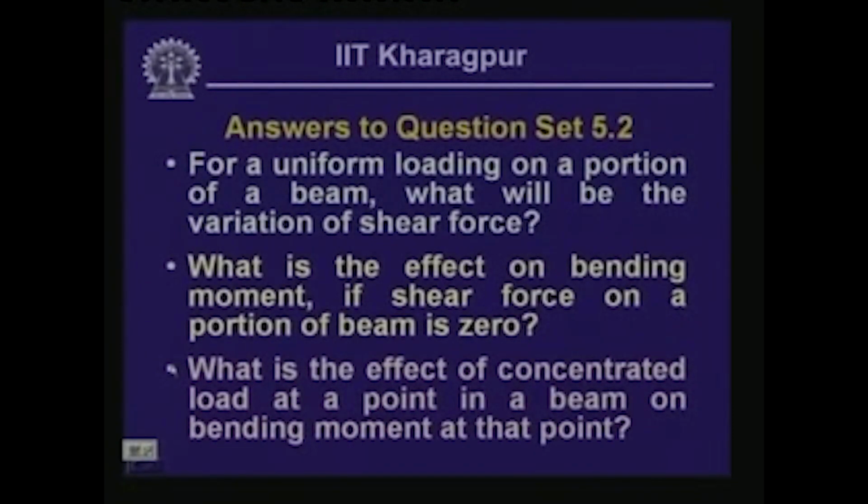Now, the last question was what is the effect of a concentrated load at a point in a beam on the bending moment at that point. If you remember, in the last lesson we discussed the effects of different kinds of loads on the shear force and bending moment at a section. The loads we considered were the uniformly distributed load, the concentrated load, or the concentrated moment. Where we had a concentrated load in a segment, we evaluated the shear force and bending moment on the left and on the right of that load.